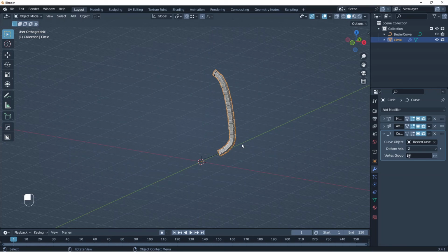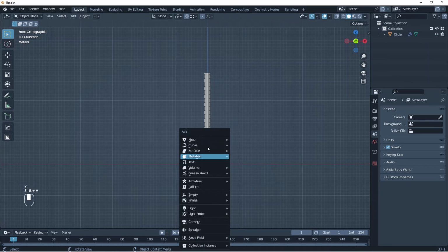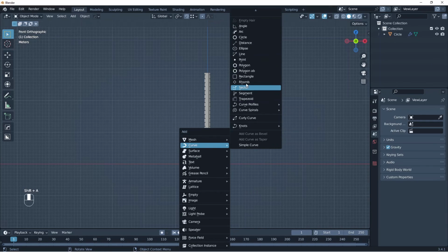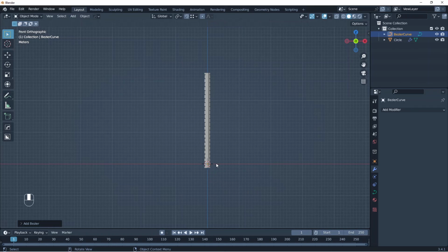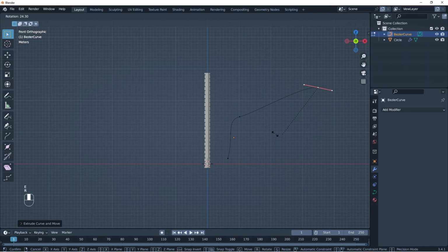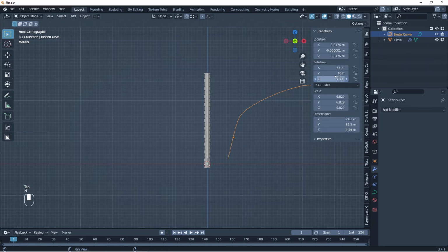But if you don't do it this way, I'm going to show you some of the problems that people run into. Sometimes you just create a curve, and then you go and move the curve in object mode however you want, just scale it, and then rotate and scale. And you see the origin is not in the middle anymore, and also the rotation is different.